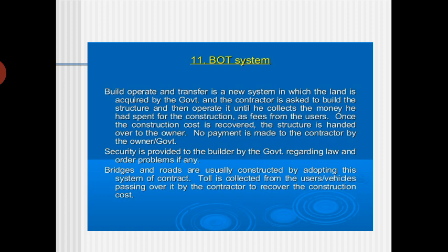When you say security deposit, during the construction phase normally about 5 to 10% of the security deposit they will keep. Even after billing they will keep about 5 to 10% of the total estimated cost. After the maintenance period is completed, they will give that back to the contractors. This is a very good system, the BOT system, where the security deposit can be kept to control the contractors.